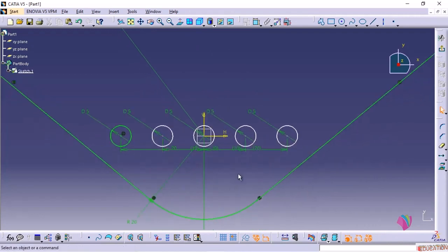So it may happen in few softwares that when you use duplication tools, the duplicates may not have the constraints that are there in the original object. It doesn't matter because those objects have been positioned with reference to the original object. So we can just ignore it. Let them be unconstrained. It doesn't matter as long as they are positioned perfectly.